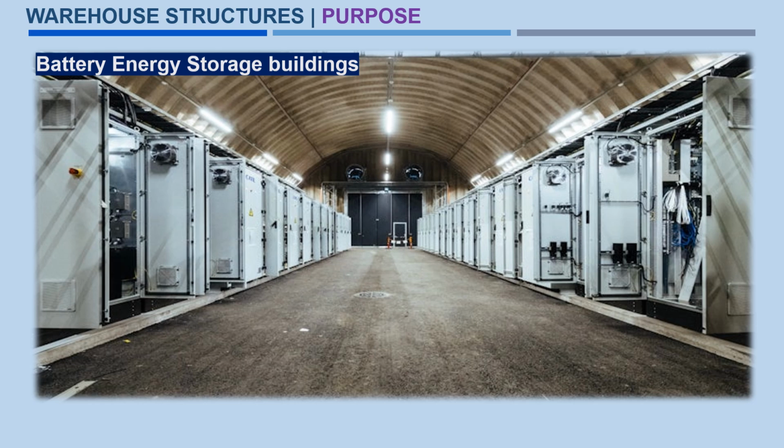So again this requires some openings or access for the battery and the switchgear panels to enter inside the building. The main thing is that ventilation is required here, because there is heat dissipation in the battery energy storage system.